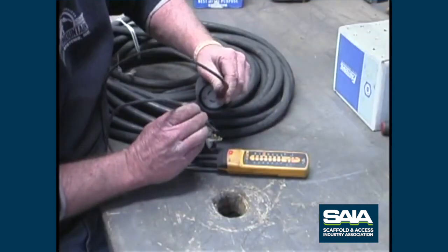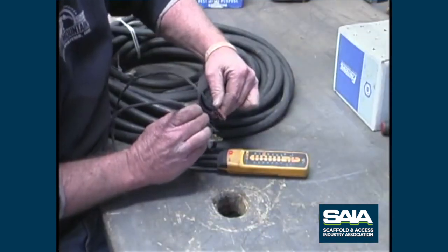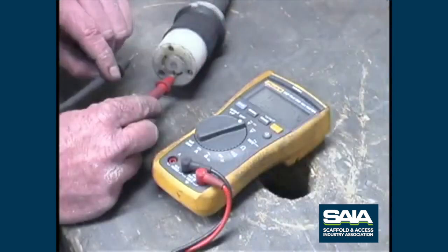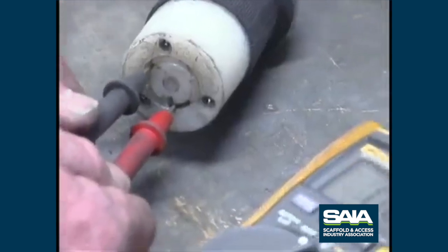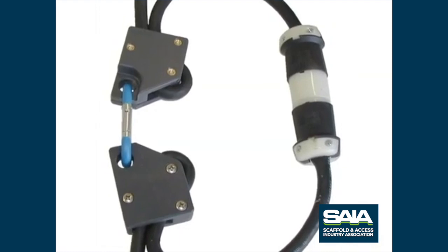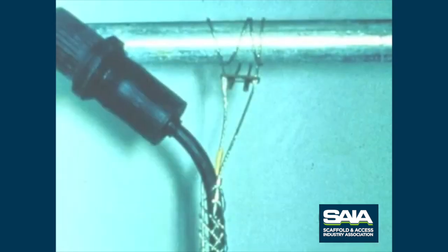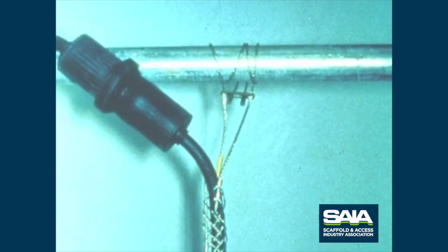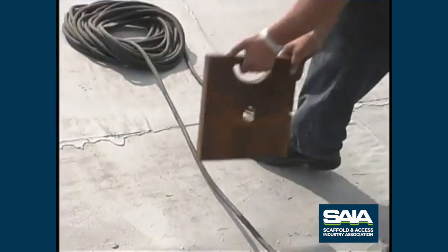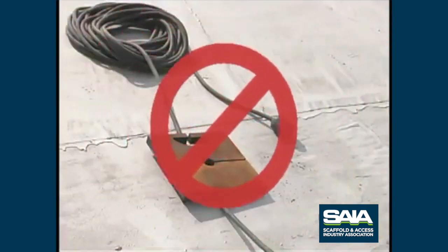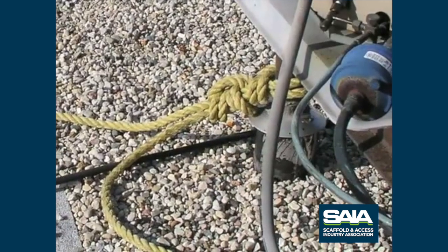Electrical cables should be properly grounded and inspected for continuity as well as for broken or cut insulation. Use only electrical cables that are sound. All connections must be of the correct type and amperage rating. Always use a strain relief device to keep the weight off the electrical connections. Knots do not work and can damage the cord. When we talk about relieving the strain on electrical cables, we don't mean by putting weight on it, as shown in this improperly rigged installation, or tying it around sharp corners.